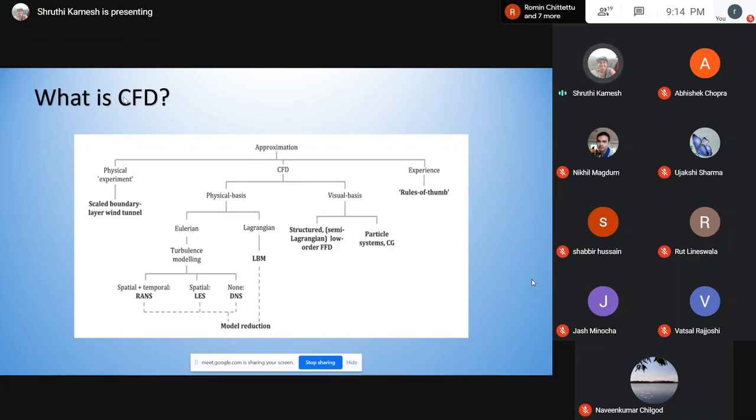So it's basically different ways of solving a set of equations to converge to the Reynolds stress term, which is the turbulence stress term, and then you can solve the main set of equations. So a very key part of Reynolds-averaged Navier-Stokes is getting the right turbulence model for your particular flow situation.